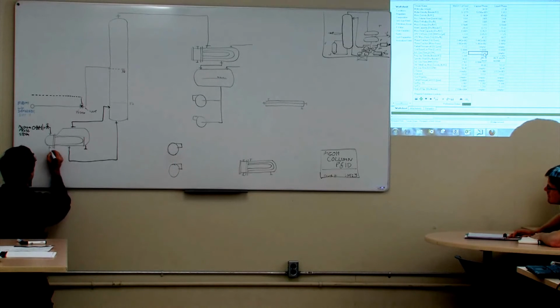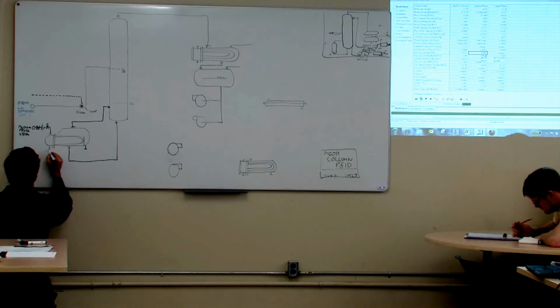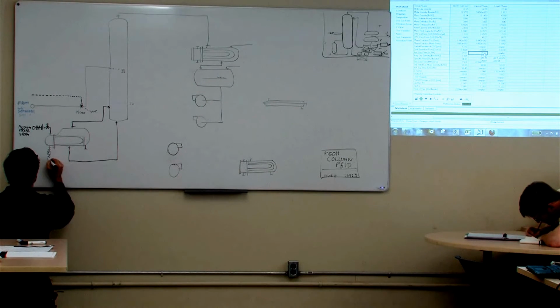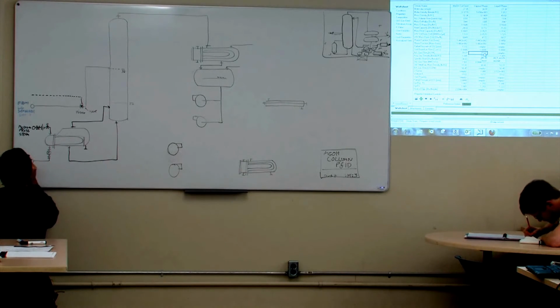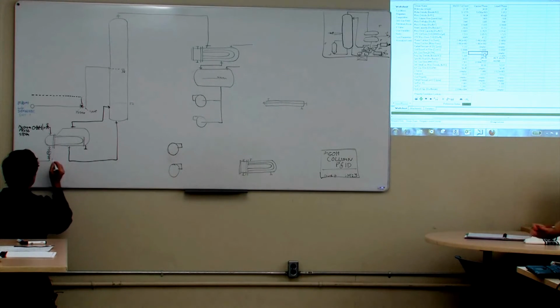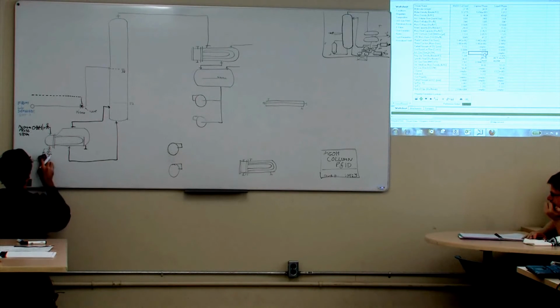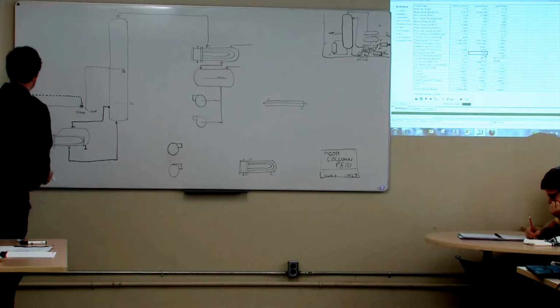My steam is going to condense in the heat exchanger, and so I'm going to come out with a steam trap to stop live steam from blowing into the condensate system. Here I'm going to break my rule, to condensate return system. So I have my steam trap in there. I'll put a little bypass around the steam trap. Whoops, valve, not steam trap. Okay.